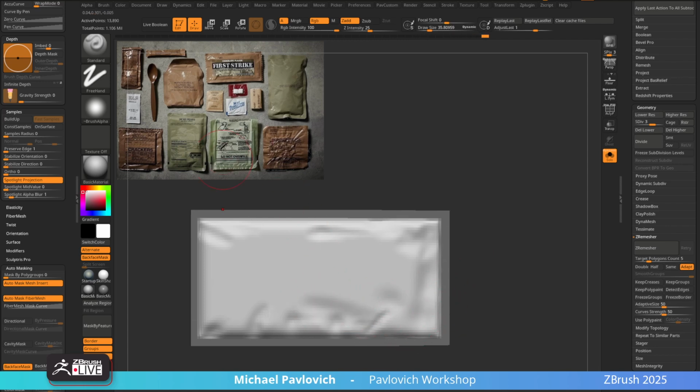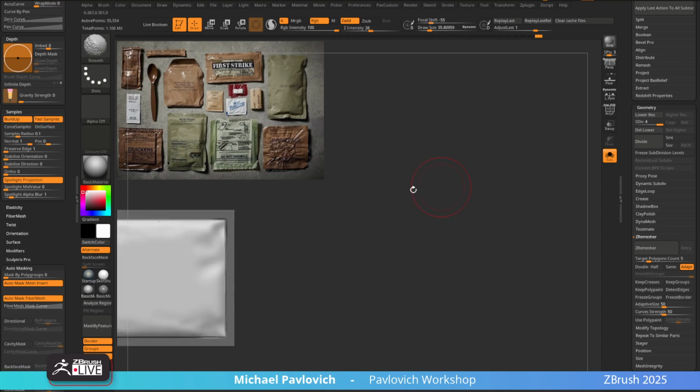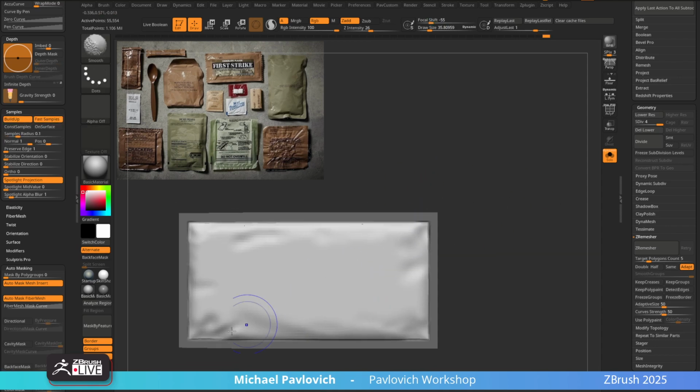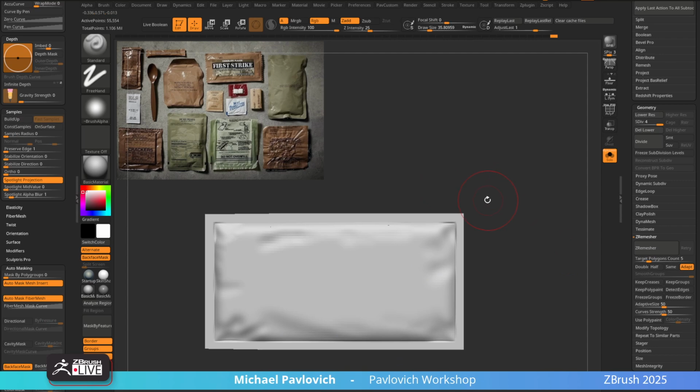But again, you could also, like we did earlier, paint this directly on there and use that as a guide. In our case, we're just gonna whatever, and then we'll go up. Oops, up one subdivision level. Smooth this out here. And then continue to refine this as much as you want. Control Shift Drag to unmask here. So now we have access to our long straight edges.